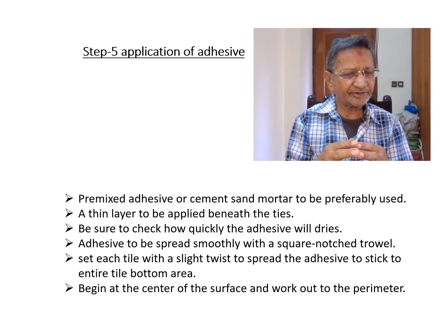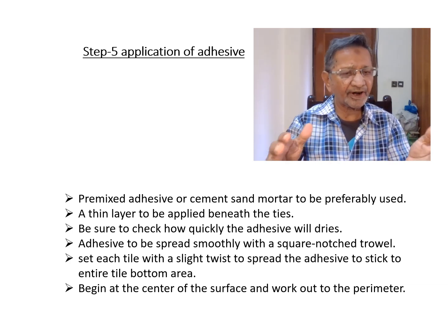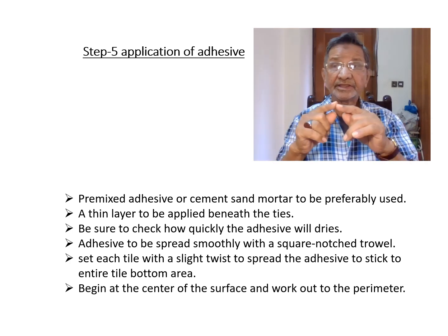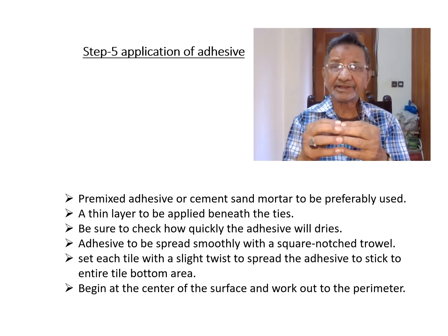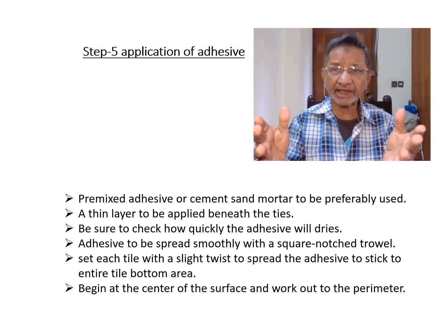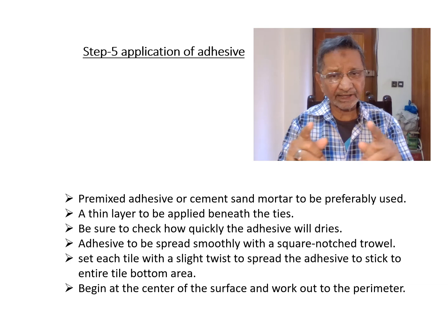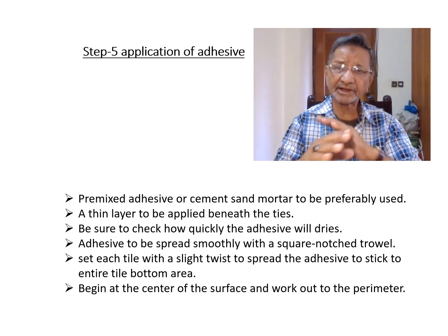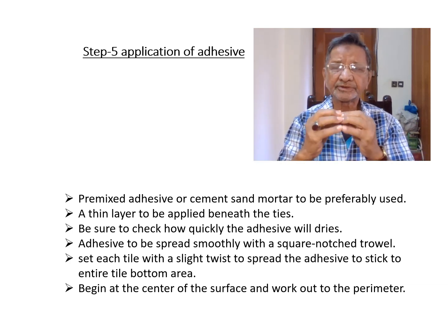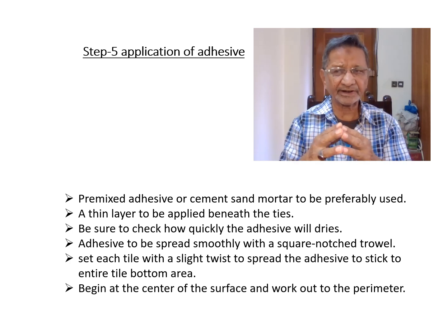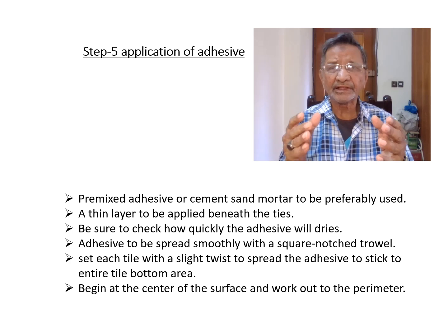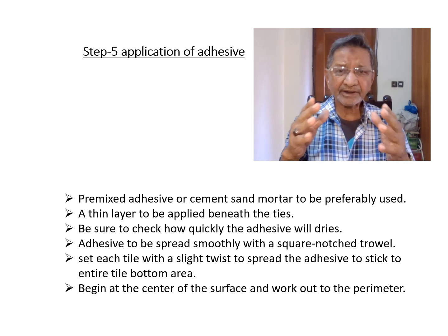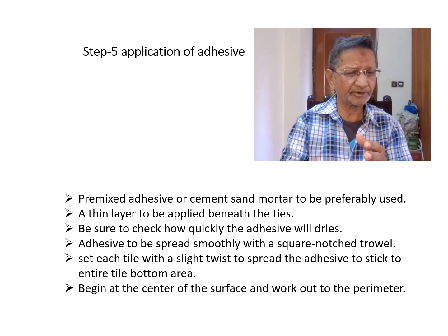Then verify the adhesive's drying time. I mean, adhesive which is pre-mixed with sand and cement has the setting time of the cement. It should not happen like that, otherwise the adhesive will come out and it cannot be stuck to the floor or wall or anywhere. So you have to be careful and the adhesive time should be checked. Even if you have purchased it from the market, the adhesive time is to be checked.